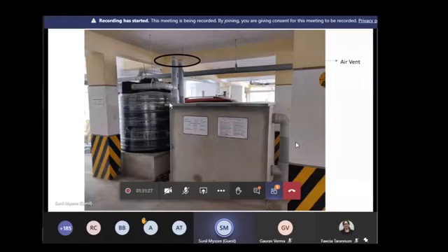Actually, nothing really can go wrong if you use a T joint, but it's better to use a Y joint as far as a first-time separator is concerned, because even for a small drizzle, you will make sure that the water just comes down and doesn't get into the further filtration.